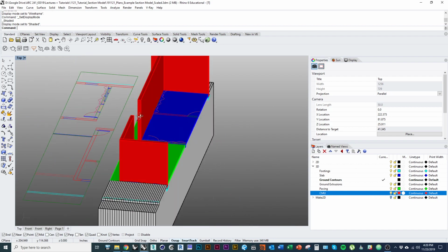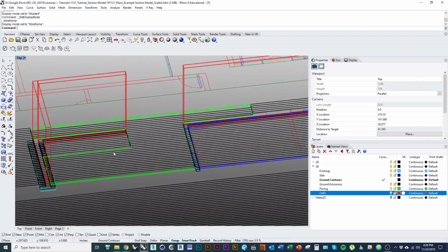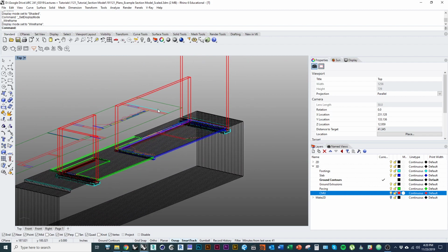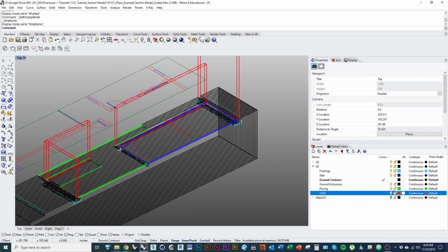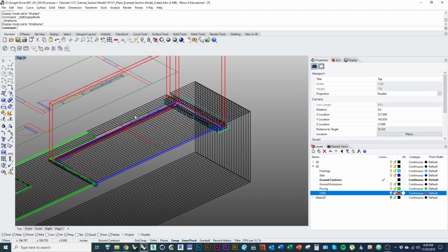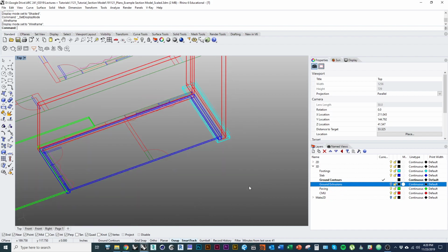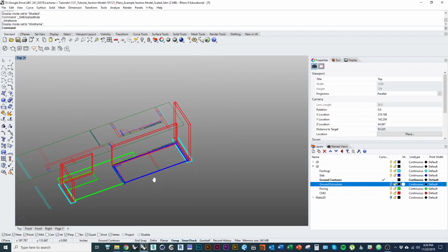So what I want to do first to complete the CMU walls is actually add my course in. If you're doing some other type of monolithic wall, concrete, rammed earth, whatever the case may be, again, you would add that kind of spacing of what the formwork leaves behind, and that should help us figure out how the windows need to line up and stuff like that. So we're going to add that right now.